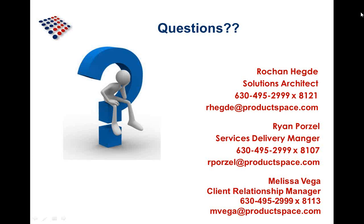Thank you, Roshan. We have another question here, and we do have time. What are the advantages to your tool over just using the Windchill tool? There are several different aspects to consider here. Windchill out of the box offers several different ways to migrate the data. So you have the import-export framework. You also have the load from file framework. And then you can also use the APIs to come up with your own custom migrators.